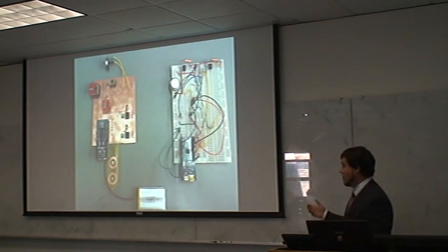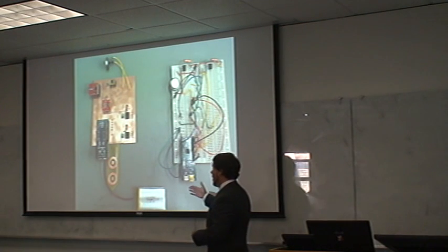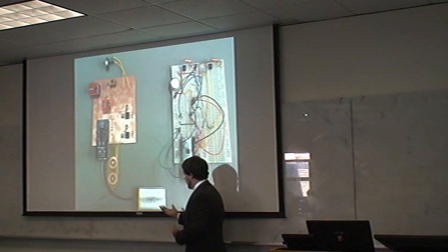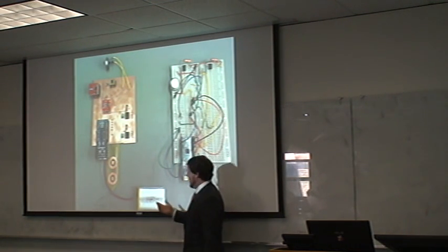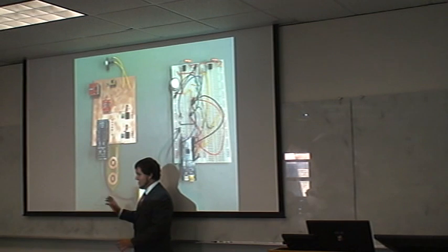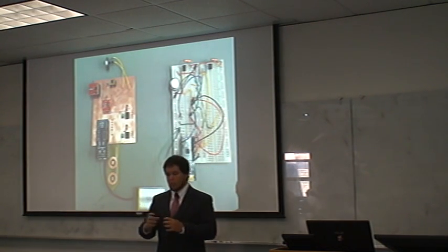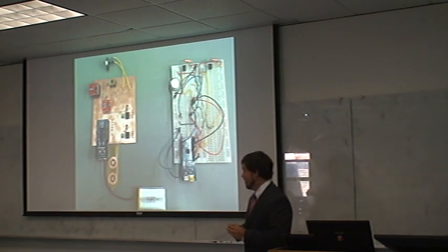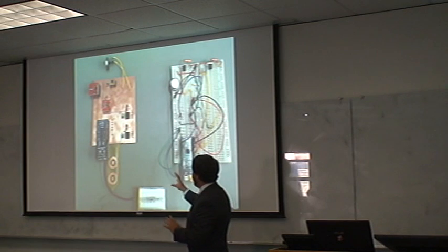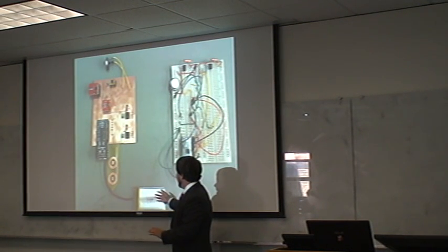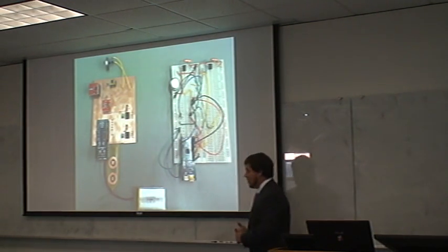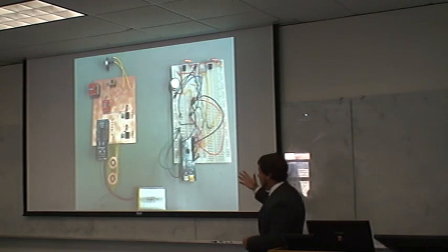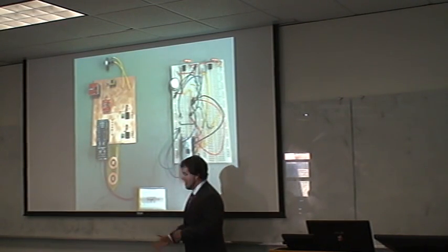After that particular prototype, we actually moved on to a copper-clad board. And this here is that soil moisture sensor that we were talking about, the capacitive soil moisture. You can kind of see a little bit better there. And the way that works is it says, okay, you've got this much soil and water between those two pads, and as you take water out, the capacitance goes down. So that right there is the geometry of that. We're kind of excited, like I said, about that. And as you can see, there's still a lot of room that we can go for miniaturization and optimization on this. There's a lot of empty space on that board. And then we still have the battery off board.